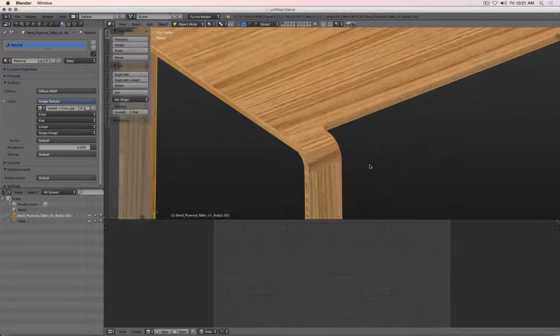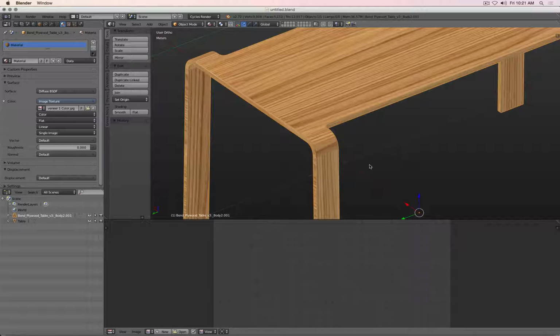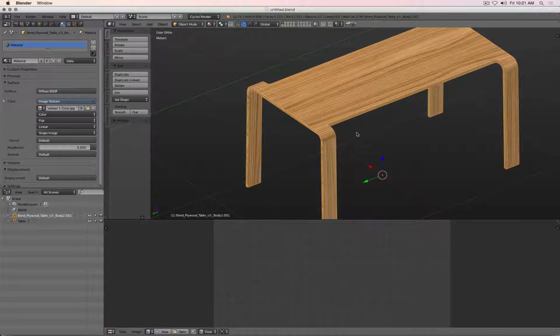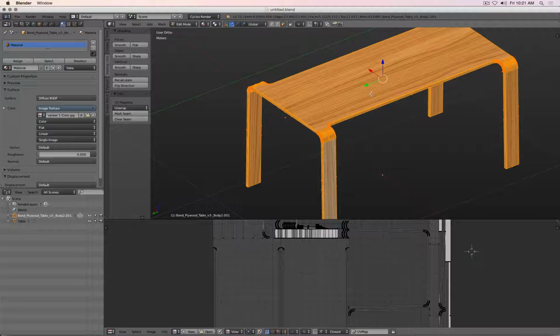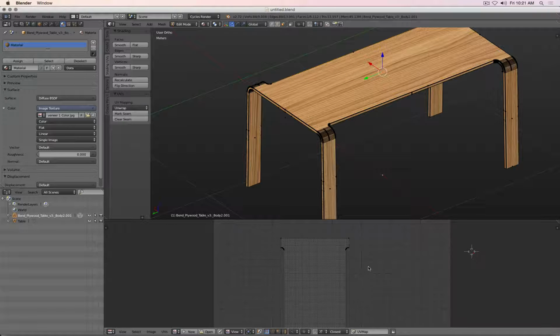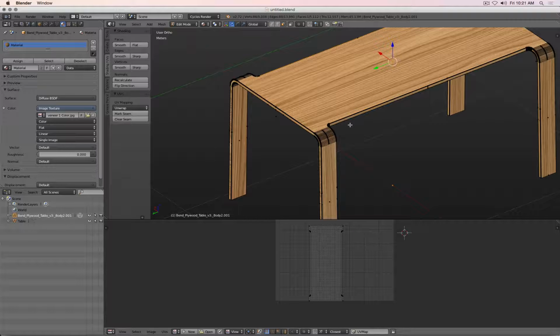So let's zoom in. So now there you can see that the wood pattern everywhere seems to have the right scale, but there's still a lot of gaps or transitional problems. And that one we can actually really easy fix. And that's one of the main reasons why, for example, meshing through MOI is an advantage, because you see here when I select this top face, it's just one face basically that describes this geometry. So inside my UV editor, I have less work to do.